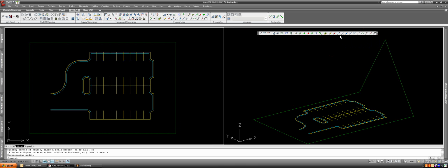Again, on your toolbar for your feature line, you should see a tool about right here called Set Grade / Slope Between Points. What this does is you select point A and point B, and you can put a specific slope between the 2 points. I'm going to select that, click our feature line.